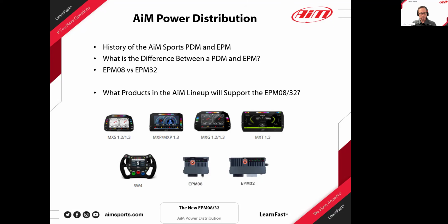So you can run dual PDMs when one PDM is not enough, or a lot of times we'll need to locate the power source, so we can run a larger gauge wire to provide power, but then we don't want to run long legs of power throughout the entire vehicle. We can now make these modular areas, front, rear, or cabin front, to keep the wire runs short. It makes harnessing a little bit easier as well.